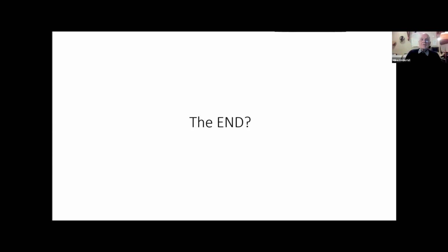Then there's another related question, this was from Philip Brown. How would you allow for antenna detuning due to human body finger proximity? So that's a detuning, not an efficiency thing. Yeah. So sometimes it depends on the antenna type. Sometimes when you hold something, it'll just give you a better match because it's just loss. You're just improving the 50 ohm match, you make it look like a 50 ohm device, but there are cases where the antenna does detune.